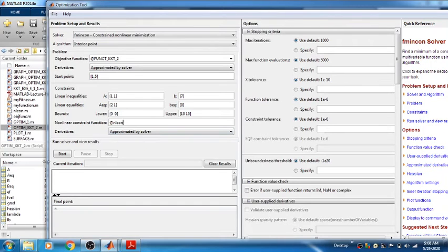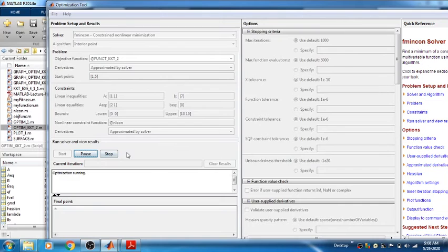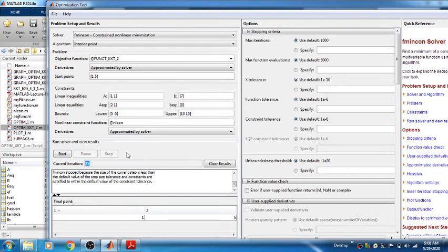Yeah. So let's run it. Everything is clear. Let's run it. After 25 iterations, I am getting the answer: x1 is equal to 1 and x2 is equal to 2. And what is the minimum? You can see it is 20, and you can see local minimum found, right, and constraints satisfied. That is the most important point you have to see in the result. So let's see the criteria, the function, all these things I am taking by default. You can supply your criteria also.